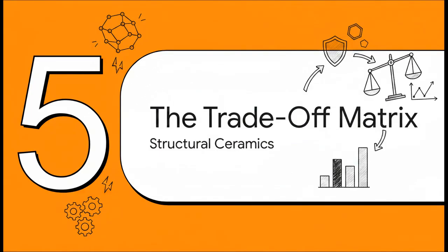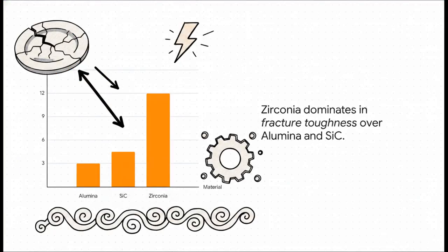Section 5, the trade-off matrix. We know no material is perfect for literally everything. So let's see how alumina stacks up against competing structural ceramics. When we line these materials up side by side, alumina's Achilles heel instantly jumps out: fracture toughness. Alumina sits pretty low at roughly 3.0 megapascals root meters. Silicon carbide is only a tiny bit better. But look at zirconia all the way up at 12. If you were designing for an environment with cyclical stress or heavy, high-impact hits, zirconia is your clear, unequivocal choice to stop cracks from spreading.